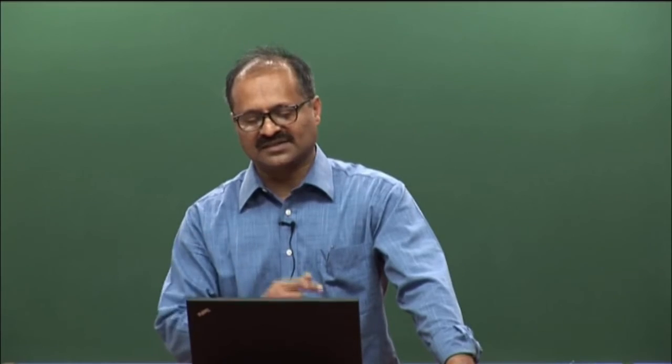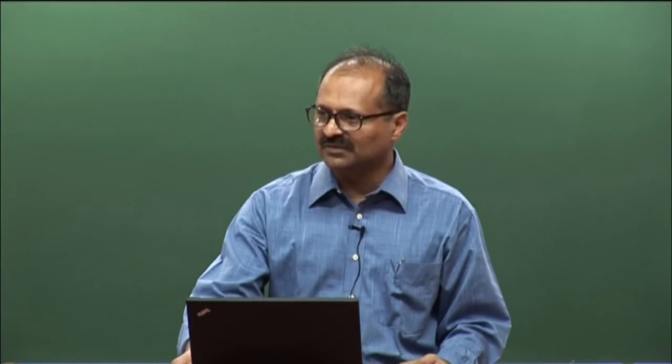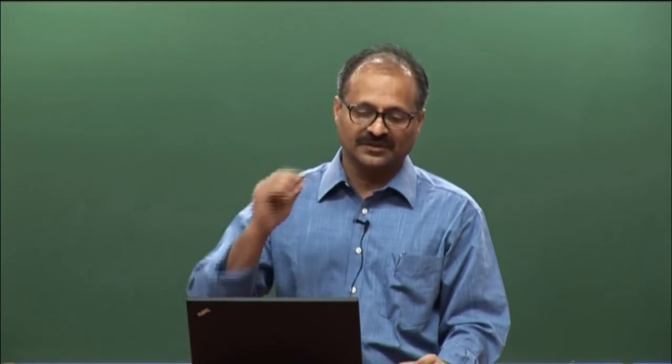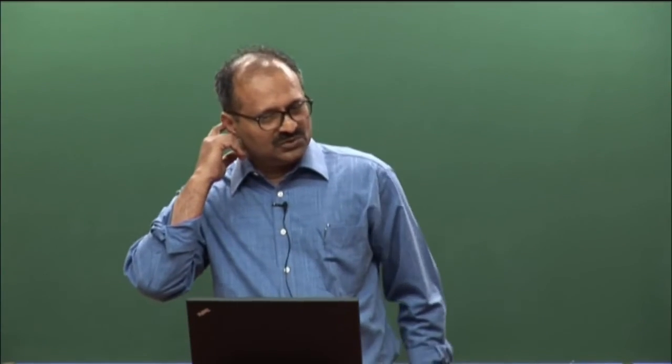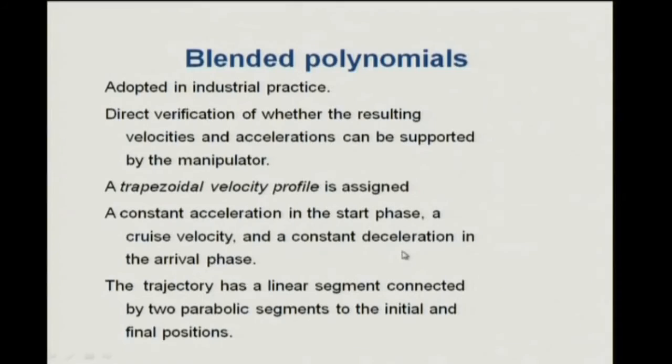In fact, if you try to match the acceleration, what will now happen is that your peak torque values will keep jumping up and down. So, it is not desirable. So, though you can fit the acceleration, it is not desirable from a practical manipulator standpoint. Okay. So, what you do in industrial practice is this thing called blended polynomials.